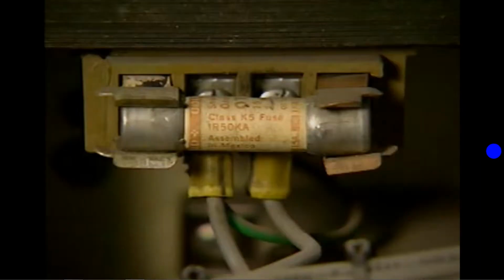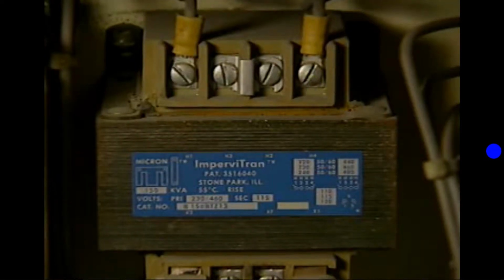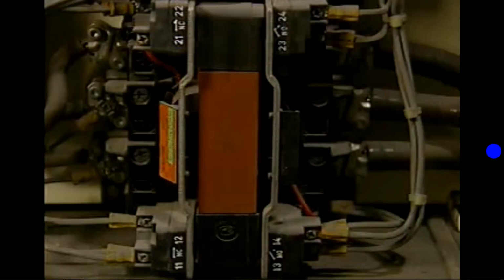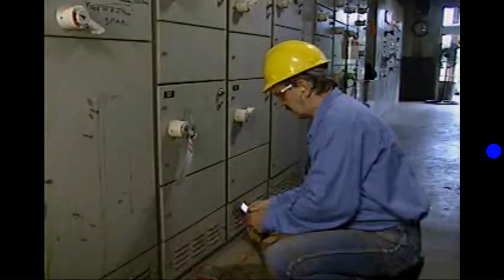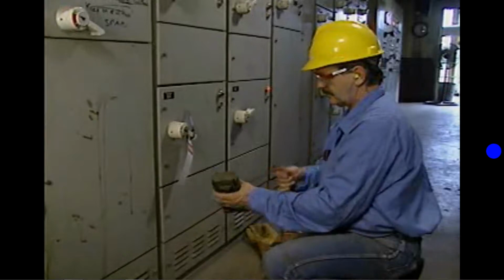If the controller is dirty, it should be cleaned with a small brush. Dust and dirt can cause binding of moving parts as well as grounds. Any loose connections can be tightened with a screwdriver. Next, the entire controller should be checked carefully for other signs of problems, such as burnt insulation and loose parts. If there are no problems, the controller's contactor can be removed, checked, and cleaned. The contactor can then be replaced, and the controller's door can be closed.